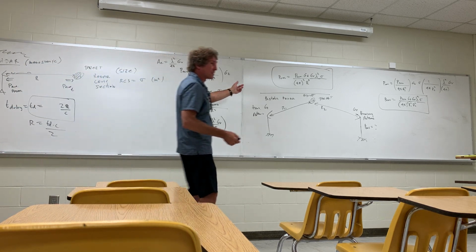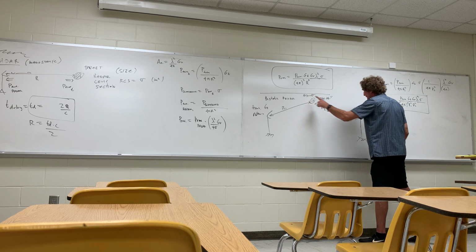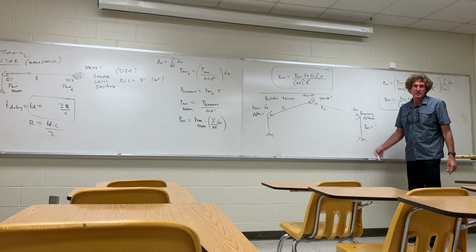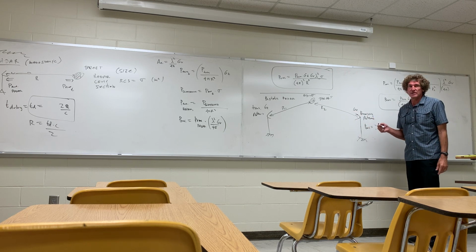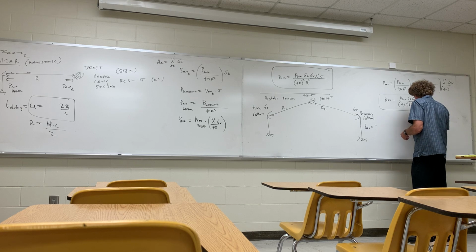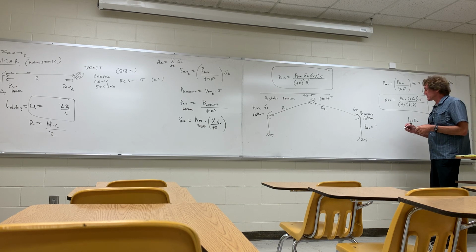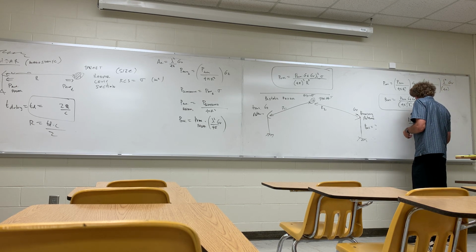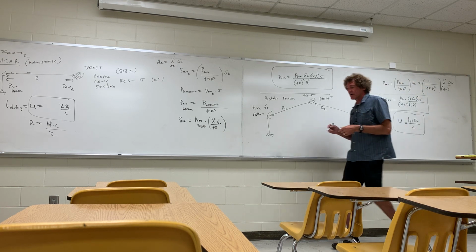How about over here? Well, what's the total range, or the total path length that's transmitted, that the signal goes through from the time it's sent to the time it's received? R1 and R2, right? So R1 plus R2 here would be the total path, right? If we divide that by c, now we get the time delay if it's actually a bistatic radar.